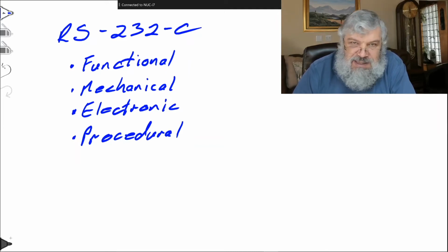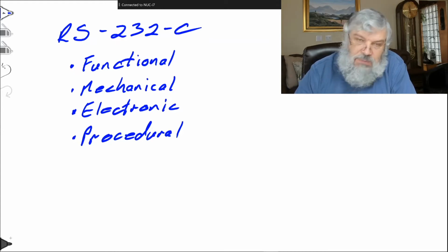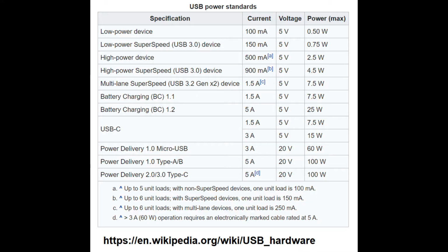Just as an aside, what we are seeing on more modern equipment, for example, the USB-C ports that I showed you just now, USB-C really talks about mechanical aspects of it. What does the connector look like? What are the electrical levels? How many milliamperes can you draw through that connector? And now we have to begin to say, are we talking about USB 3.0, USB 3.1, USB 3.2, and names such as Thunderbolt gets thrown in there.